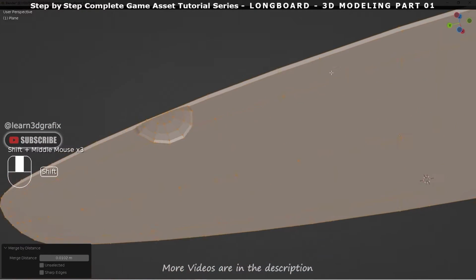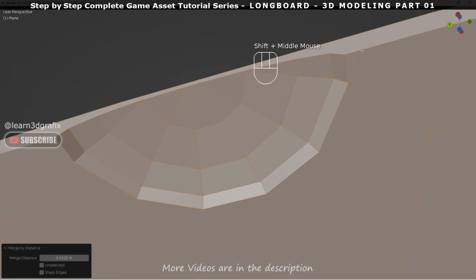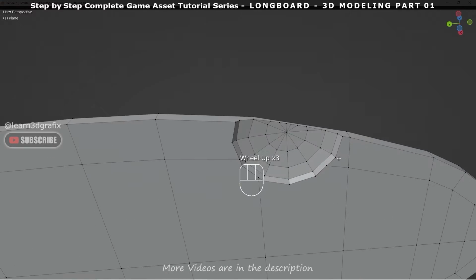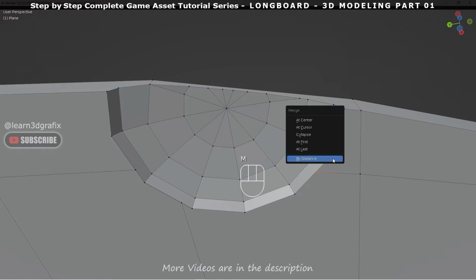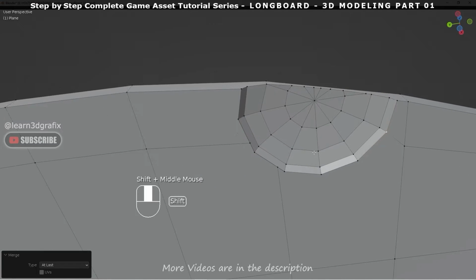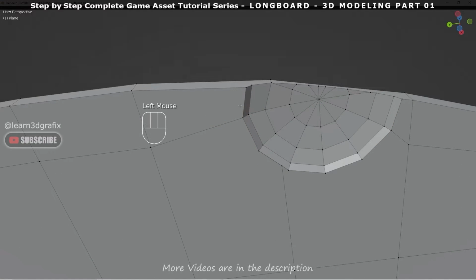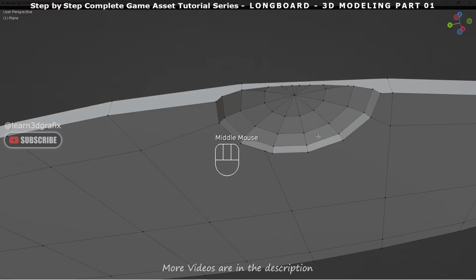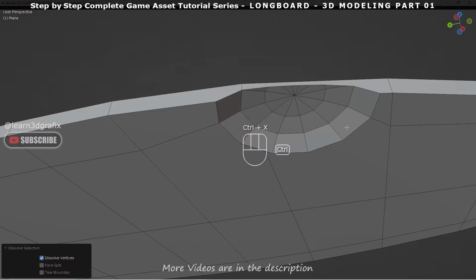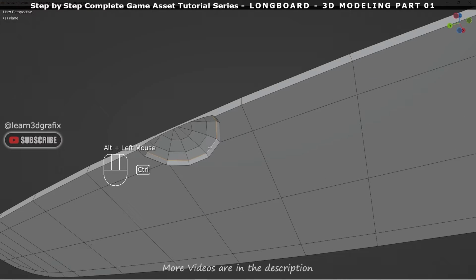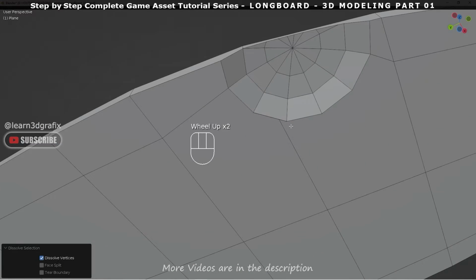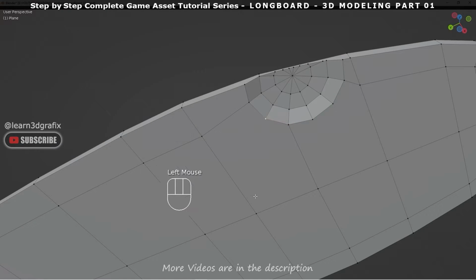Closely check the mesh for any issue. Now the mesh looks fine. We will now remove the n-gons created during the Boolean process. Select these two vertices, press M and choose option Merge at Last. We have to keep the mesh as low as possible right now, so I am removing some edge loops. Select these two vertices and press J to join them.